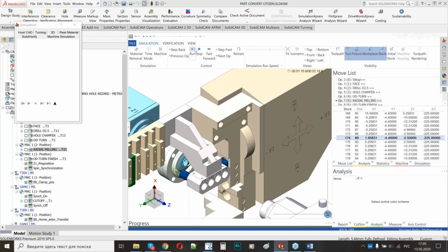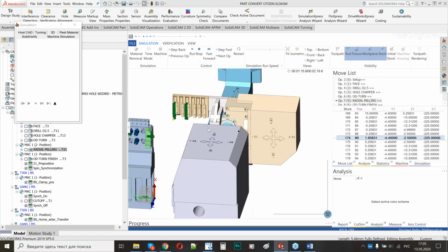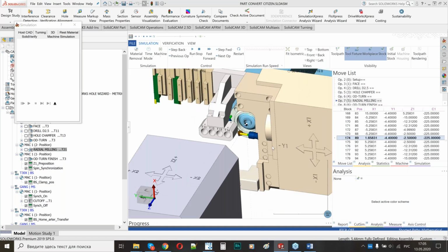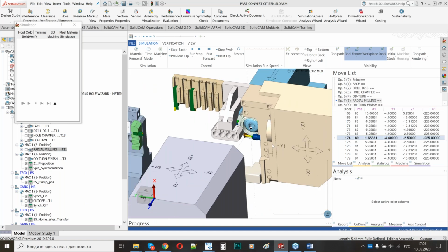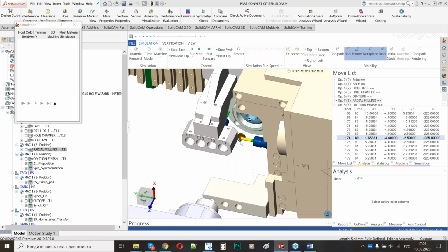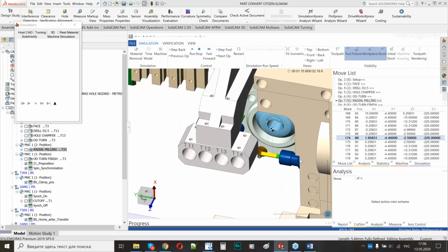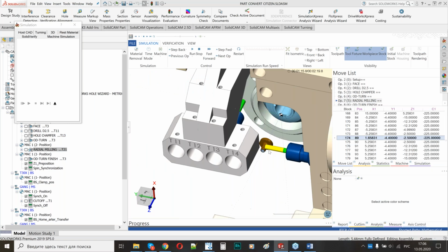And for this machine, as you can see, the tools for the radial milling are located in some other place. It is rotated by 90 degrees here, but I didn't change anything. I didn't add an additional coordinate system or recalculate the process, or re-choose the tool. I just put the tool in the right position, and I know this tool can do this.